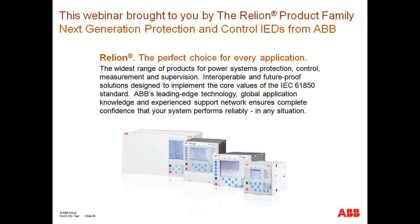Okay. For a short period of time, just like line differential, they will continue to have the capability of operating, because the drifting time of the clocks of devices these days is quite finite. But at some point, if the synchronization does not come back, at least the devices that are subscribed to that particular datagram will not be able to make use of that information.